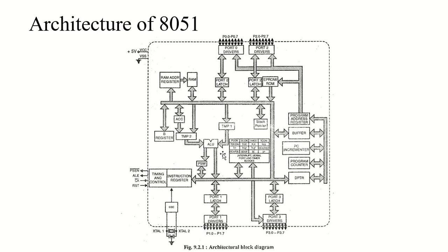So after that we have the input and output ports, except that we also have the special function registers which are placed in the address space immediately above the 128 bytes RAM, from address 80H to FFH. Now the 8051 microcontroller operations which don't use the internal 128 byte RAM are accessed by a group of specific internal registers, which are called the special function registers.